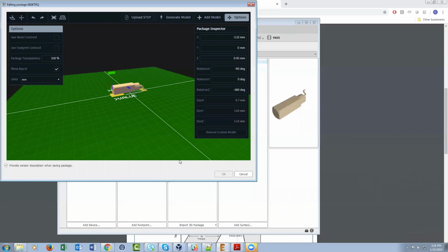Usually, what I do when I have any issues with a step file, the first thing I do is try it in Fusion 360 to make sure it's good. And then if it is, I export it as a step again from Fusion to see if it cleans it up.